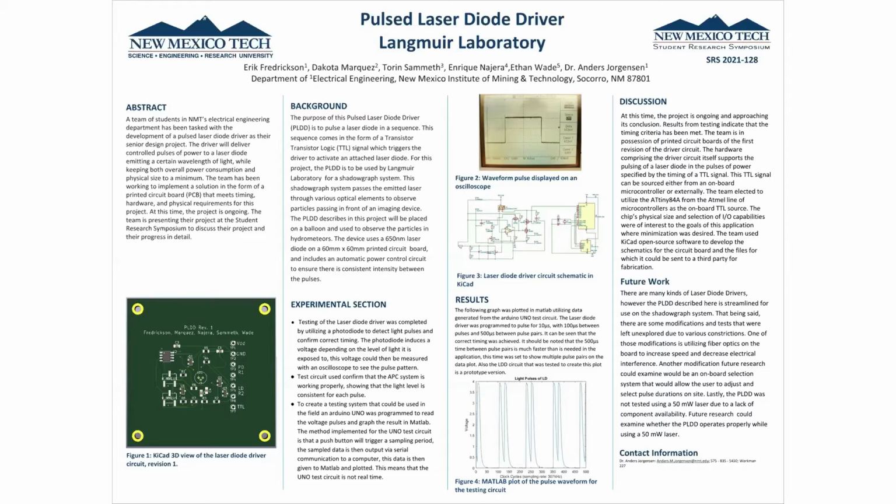We decided to use the ATtiny84A chip from the Atmel line of microcontrollers. It was selected because of its physical size, as well as some other parameters that matched up with a lot of things that we needed to keep to a minimum in this project. We didn't necessarily need a really fancy microcontroller with all the bells and whistles, just a simple one that has very basic I/O capabilities. And as I mentioned, we use KiCad open source software to develop these boards.